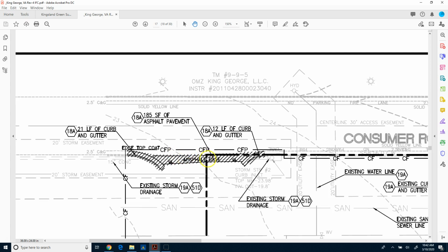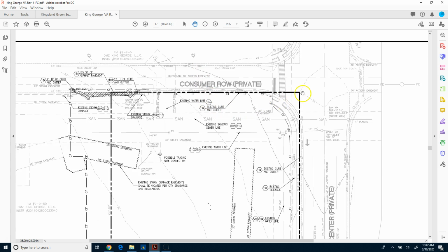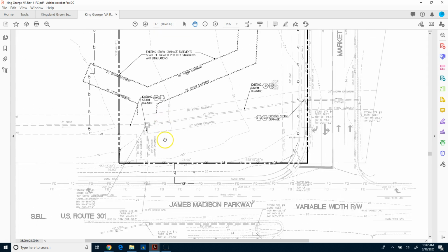But if you remember, they found a nail and a benchmark is in this location right here. So that means that if we plan on using that information or that nail, once they start demolition, that's going to go away. That's going to be gone. So you probably want to plan appropriately to make sure that we put some other resource or some other control point on the site somewhere where we can use it, where it won't interfere with the construction process. So, again, looking at the demolition plan to determine where to put control is probably going to be a good thing, especially even on your grading.